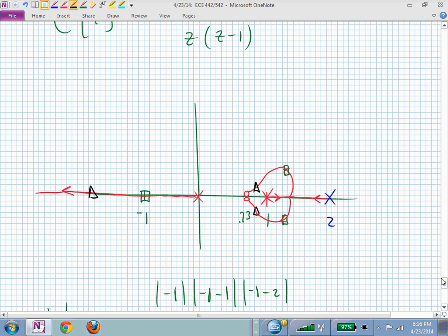And these triangles were on the root locus, weren't they? Darn things, though, they gave us an unstable closed-loop system because we had to crank up the gain more than we wanted to get to the triangles. So that means maybe that 0.8 plus and minus j2 is not where we want it to be. Where should we go? This is why you're getting paid the big bucks after a class. Any suggestions? Any ideas?